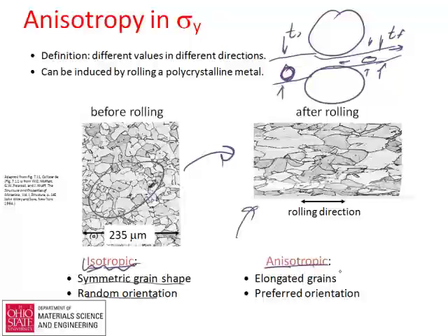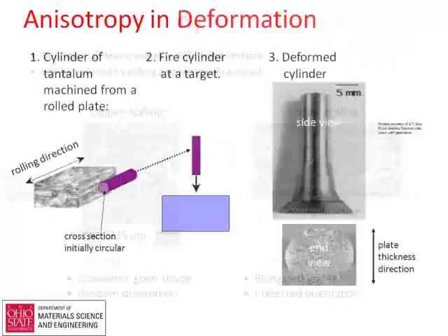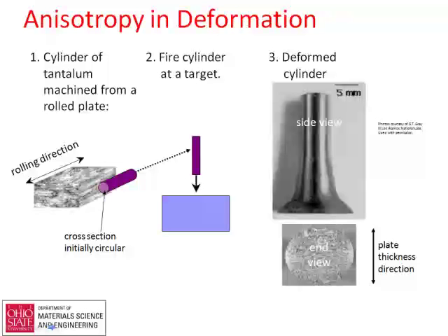And there are two sources of anisotropy. First of all, you've got elongated grains. Then secondly, you may or may not have preferred crystal orientations. But you can certainly see that there are elongated grains in that case. Again, that's something we can control and use with great power sometimes.